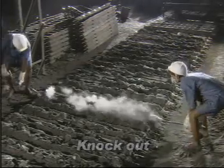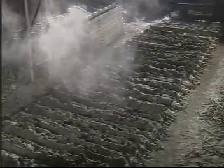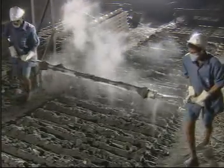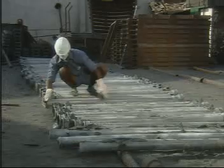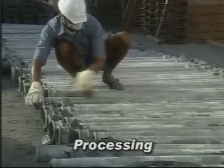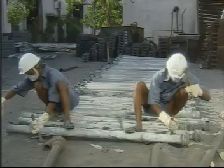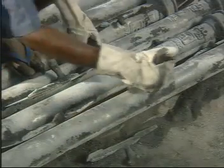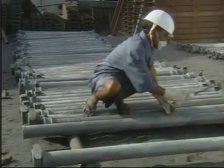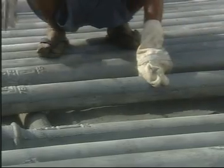After manufacturing of the pipes, processing is carried out, along with a number of quality checks to ensure that our products meet all requisite specifications. The cast pipes first undergo cleaning of the inside and outside surfaces with a wire brush. They are then visually inspected. Thereafter, the excess metal runners and risers are chipped off. A hammer test is now carried out for soundness of casting. This is followed by grinding.